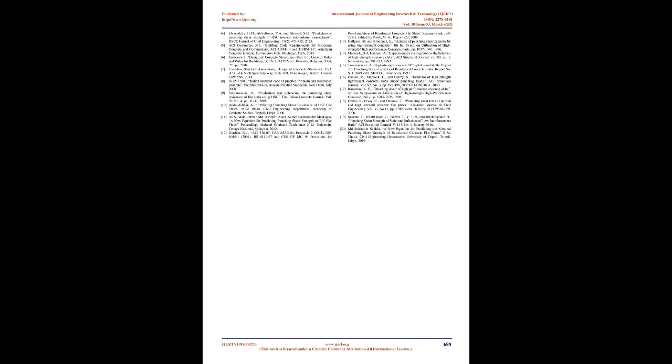1. The proposed equation is found proportional to the square root of the compressive strength, to the cubic root of the reinforcement ratio, and to the effective depth, and it assumes the critical perimeter at a distance 0.5d from the column face as defined in the ACI 318-14 code. The punching shear strength of plates is a function of the flexural reinforcement ratio, and the investigation shows it is proportional to a power of 1/3 for ρ and a power of 1/2 for f'c. This proposed equation is in good agreement with other code equations, yet it has a very simple form and is valid for a wide range of normal as well as high-strength concrete flat plates. The proposed equation has the following form: